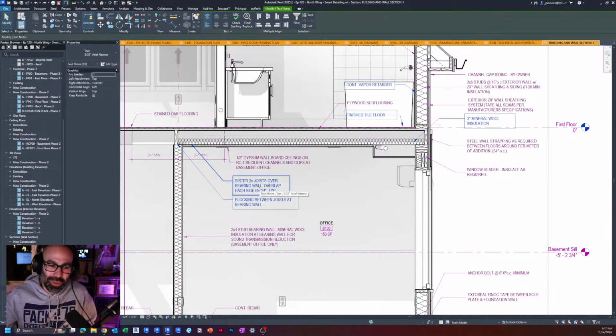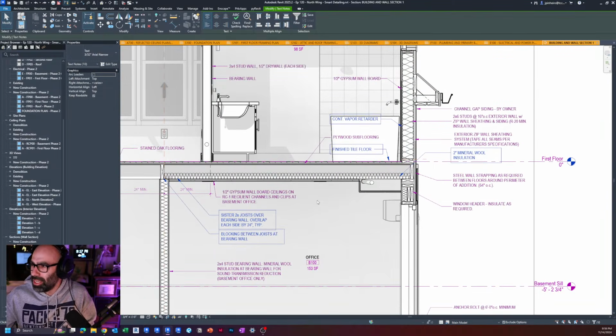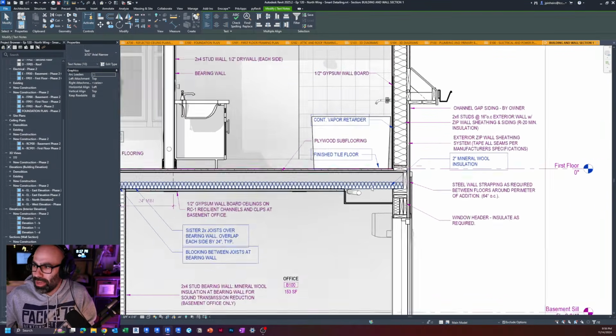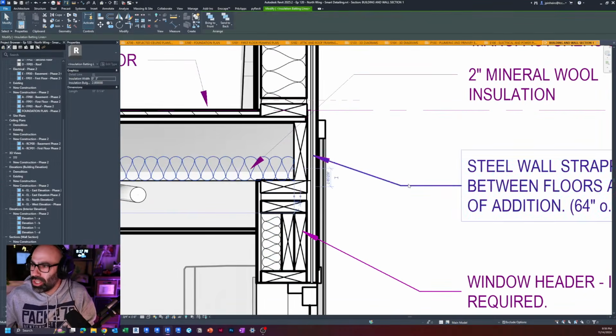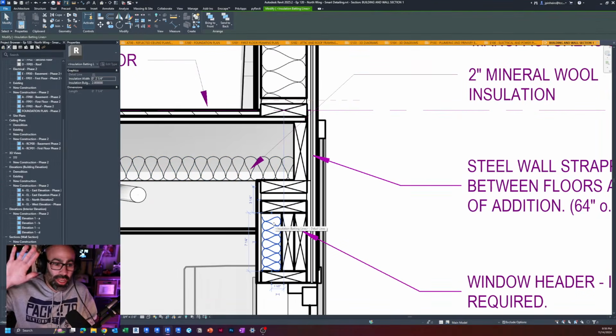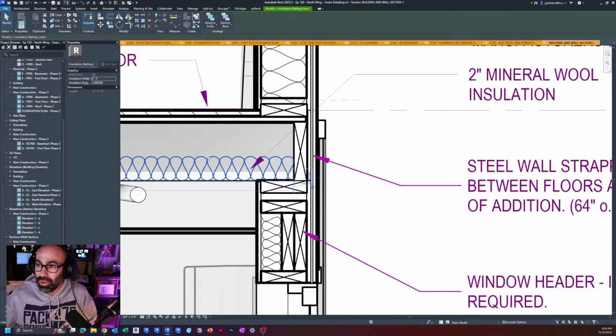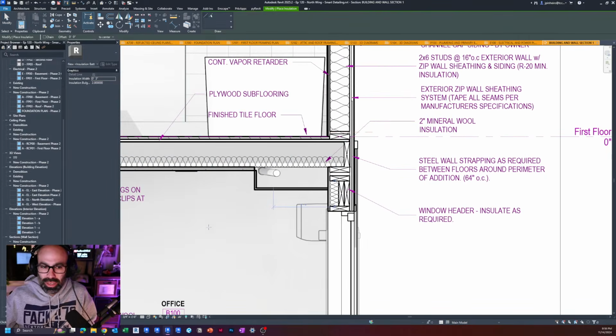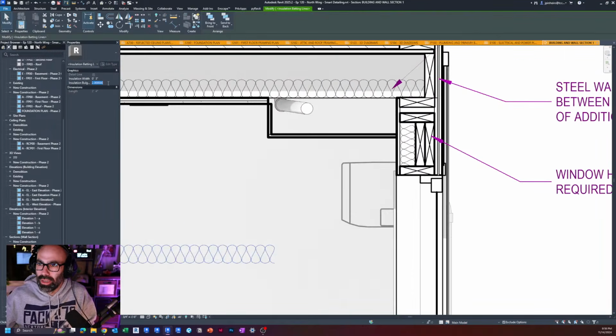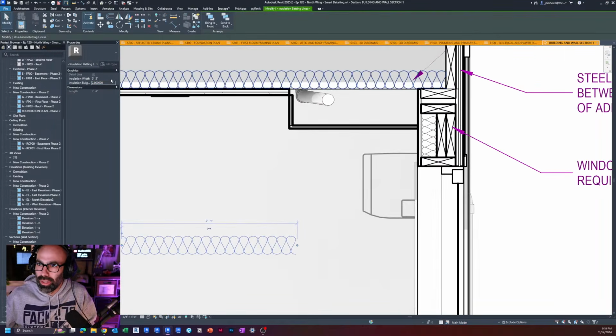I guess I'll jump into limitations real quick. This is a limitation in general of Revit, if you use the insulation tool. Anyone who uses the insulation tool, raise your hand. It's actually a great tool, right? If I click create similar, you just draw a distance, and you can change the bulge as well as the thickness of it, right?